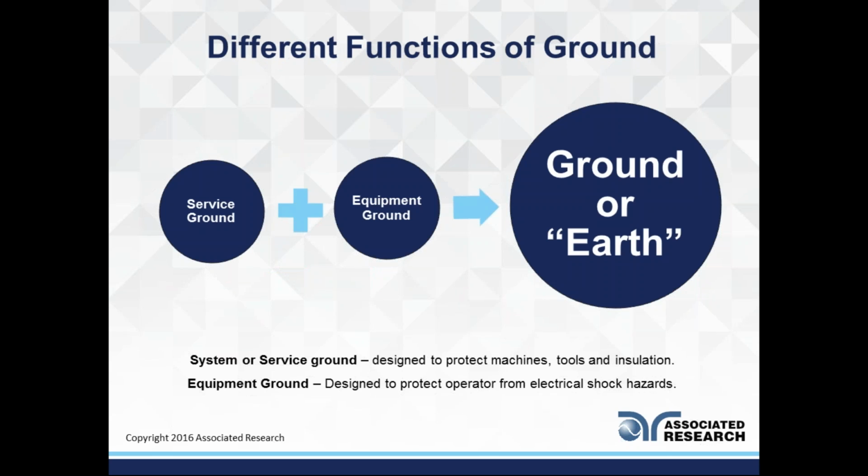There's obviously different functions of ground. We have a service ground, which is kind of what we were referring to in the last slide, or what probably everyone watching this webinar is here for is your equipment ground. You know, the ground that is inside your products or DUT and is meant to catch any fault current. So we refer to that as ground or earth.